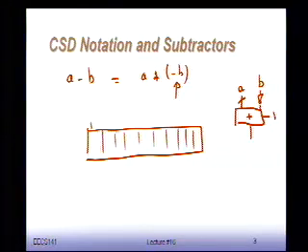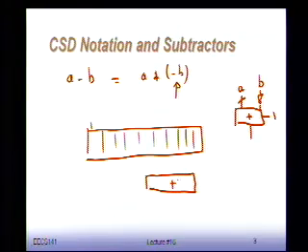So I can use a simple full adder, add inverters to all of the second input, and change the carry in from 0 to 1. And you're done. So that's beautiful, right? There's very little overhead. Now with this extra money, I can change my adder into something that's a programmable add subtractor.